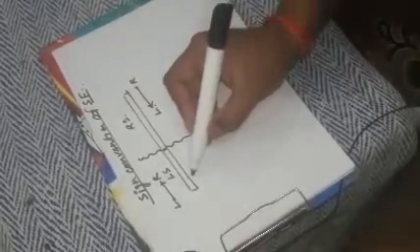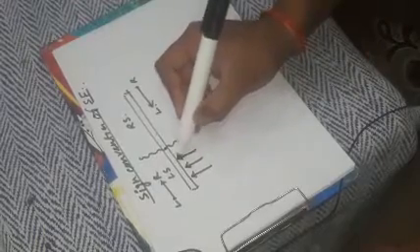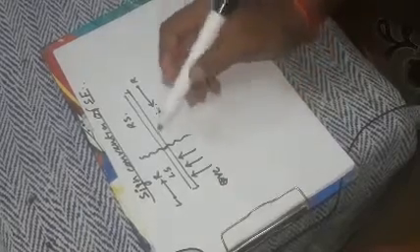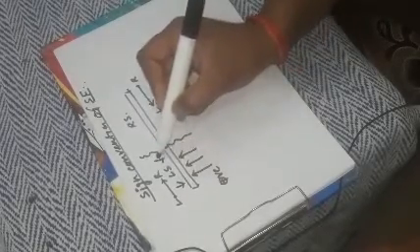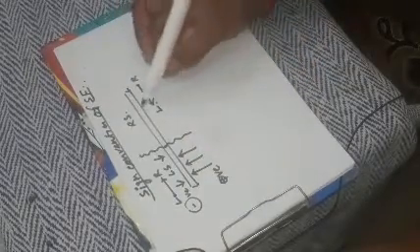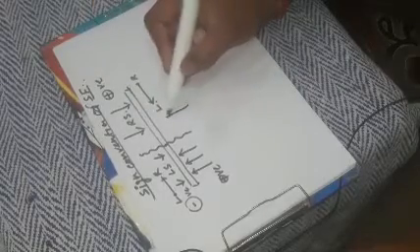During the analysis, all the upward forces on the left segment of the beam will be considered positive and downward forces will be considered negative. In case of the right segment, it is just the opposite of the left segment. All downward forces will be positive and upward forces will be negative.